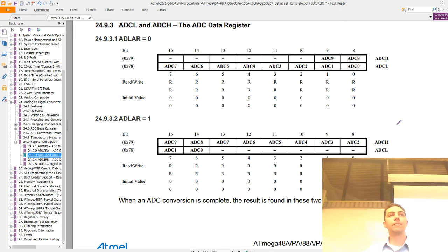So if we had a button set up to interrupt 0 or 1, that means that we could have had it not use a button interrupt and then check the thing. We could have had it set up to rising or falling specifically. Unfortunately that dev board does not hook up the onboard button to D2 or D3. So you had to use a pin change interrupt to do that. You could have hooked up an external button, another button, and then pressing that button, you could have chosen rising edge or falling edge, and then it would have automatically triggered.